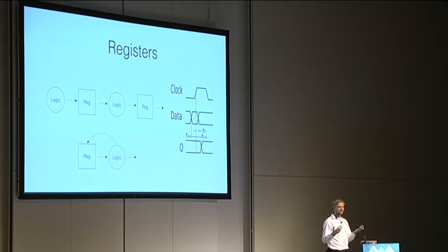You know that your CPU, for example, has a clock. And on every rising edge of the clock, it does something interesting. It stores the data that is on the input, and a little bit later, it puts it on the output. It just captures the input at a very specific moment of the rising edge.